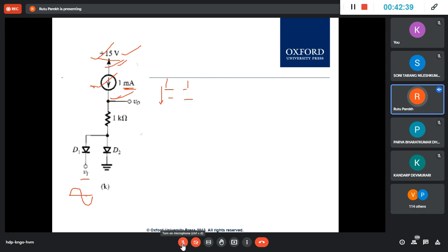So this is a king, this is the boss. So you have to forget this. Whether it is 1500 or 50, whatever, right? You forget this and you take this as your circuit now. So you start from here and you take this as 1 milliamp, which is going to flow through here. So your circuit is now reduced and this is no more there.